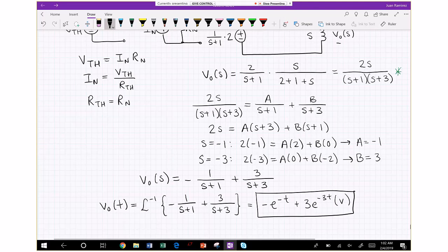Alright, so essentially it's that. You get a circuit that'll have R, L, and C components in it, as well as a voltage source or a current source, or maybe both. And those voltage and current sources are usually time varying. If they weren't time varying, then the analysis would be really straightforward, because the inductor would look like a short circuit and the capacitor like an open circuit. But because the input is time varying, then you have to analyze the circuit as a transient circuit.